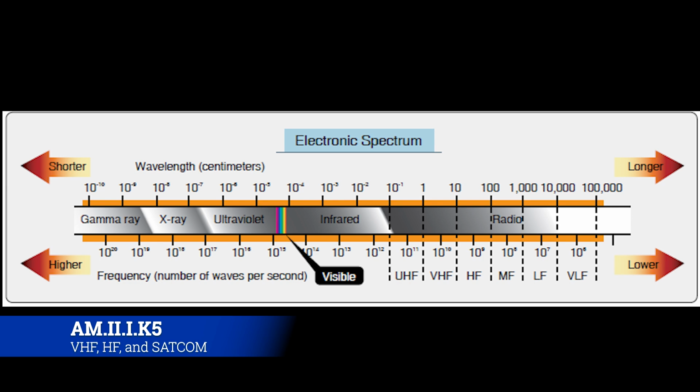That's all infrared stuff. If you ever go work on the military side of aviation, this particular spectrum of light will become really important to you, because there are a lot of landing lights that are infrared. There are position lights on helicopters and airplanes that are infrared. The reason being is that you can use the benefits of night vision goggles because they can see infrared, and it's like the lights are turned on and everyone can see everybody.